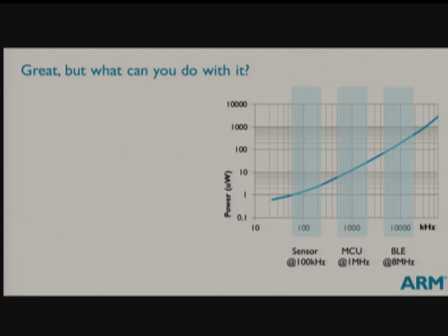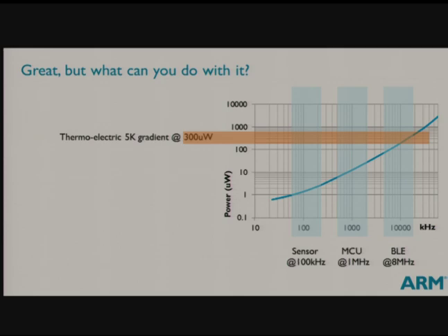And you can overlay onto that, then, what are you going to use? And I'm being counterintuitive here. I'll put energy scavenging at the top. If you're alive, and you're not wearing too many clothes, you can maybe get that 5K, 5-degree thermal gradient, and you can therefore probably generate 300 microwatts. So it's enough to actually run Bluetooth LE for your Bluetooth-enabled bandage that is getting its heat from you. It doesn't need to have a battery. You can just about do that. You're maybe running an MCU, and that's 5 years continuous operation at 1 megahertz off a standard coin cell battery.